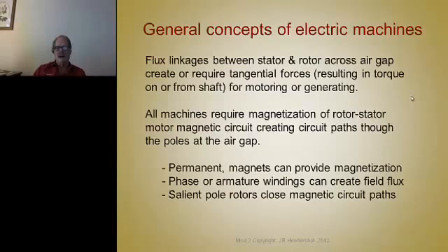The motors that are used in your house, in your refrigerators and your washer and dryer and your household appliances, they're in the 1 to 2 psi air gap stress requirements. And what that is, a force is created in the air gap times the radius of the air gap is the torque on the shaft. So the stress is that force generated, or the torque generated, converted to a force by dividing the radius back out,